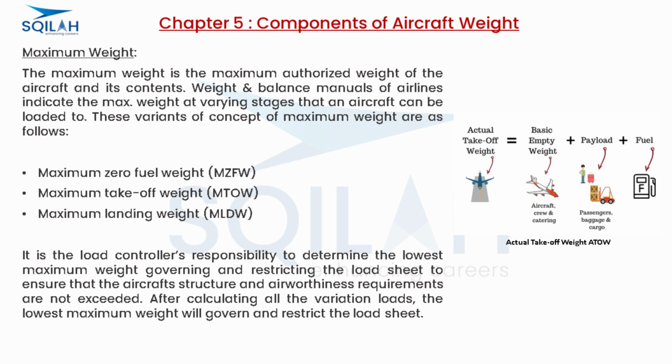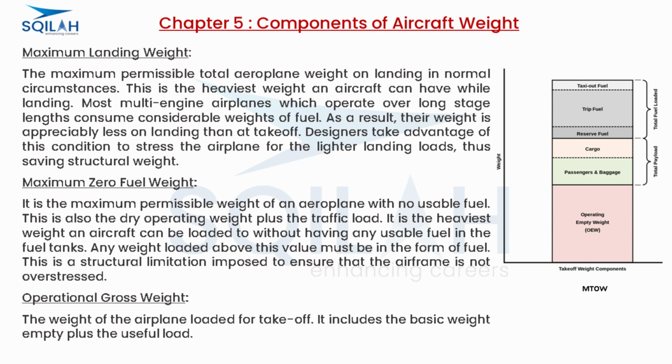Maximum zero fuel weight, MZFW. Maximum takeoff weight, MTOW. Maximum landing weight, MLDW. It is the load controller's responsibility to determine the lowest maximum weight governing and restricting the load sheet to ensure that the aircraft's structure and airworthiness requirements are not exceeded. After calculating all the variation loads, the lowest maximum weight will govern and restrict the load sheet. Maximum landing weight. The maximum permissible total airplane weight on landing in normal circumstances.